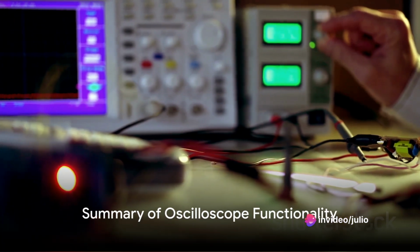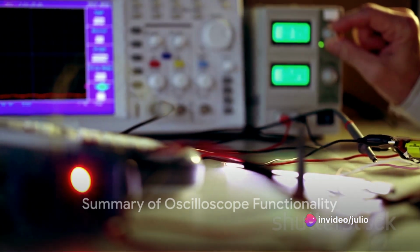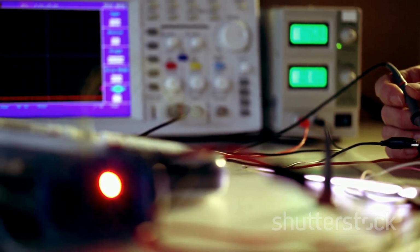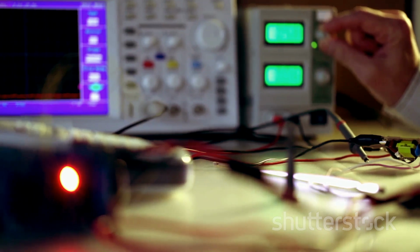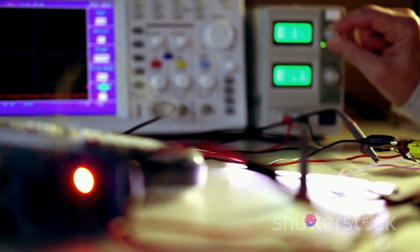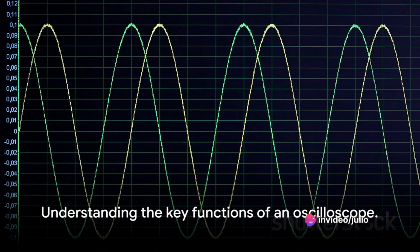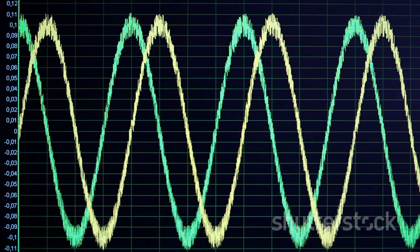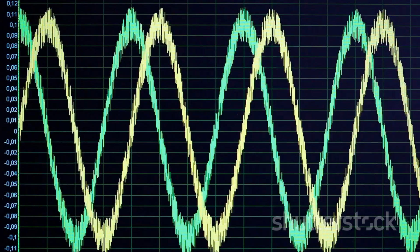So, to summarize, an oscilloscope works by taking in a signal, amplifying it, and then using deflection plates to plot it on a screen. The vertical movement of the plot represents the signal's voltage, and the horizontal movement represents time. The oscilloscope also has a time-based circuit to control the speed of the horizontal sweep, and a trigger function to control when the sweep starts.